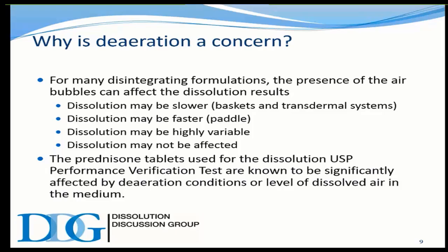Following up with prednisone, speaking of drugs that are affected by deaeration or lack of it, this has a profound effect on release rate for the performance verification test based on the prednisone tablet. These are very sensitive to dissolved gases, and results are virtually double at the early time point, which for prednisone is 30 minutes. And so for that reason, the deaeration process and the method that's used is effective, and it has to be proven that it's effective as well.